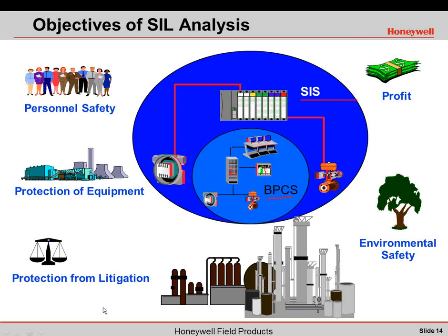You could think of it as two different worksheet types that either allow operation as a safety system or as a process system. But the two systems still have to be separate. Otherwise they would have what are called common cause failures. So they can be the same type of controller, but they cannot be the same exact controller, as long as that series of controller has a safety controller as part of its offering. Right, as long as your safety controller does have a SIL rating. Correct.